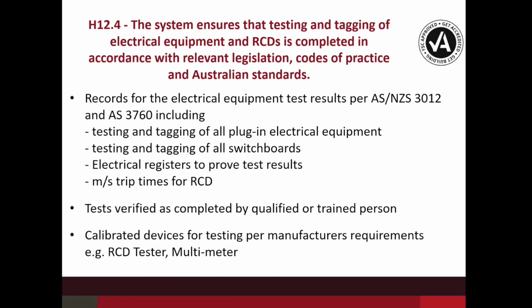We then also go into calibrated devices. Now, one of the things that we do highlight in the industry, RCD testers are great when they come out of the box. About 12 months later, usually 12 months, they're required to be calibrated. Again, something that takes such a very close measurement needs to be calibrated to make sure that it's still working. Because again, if we come and test it against another machine and it's not calibrated, then we end up with an RCD that's potentially out of balance and doesn't operate quickly enough and then exposes potential persons to risk.